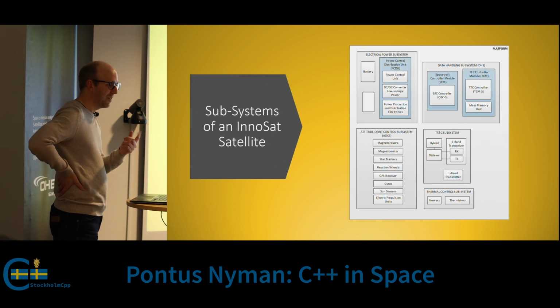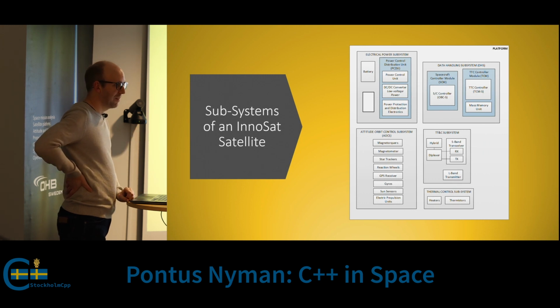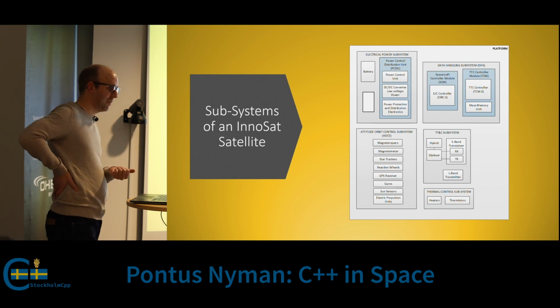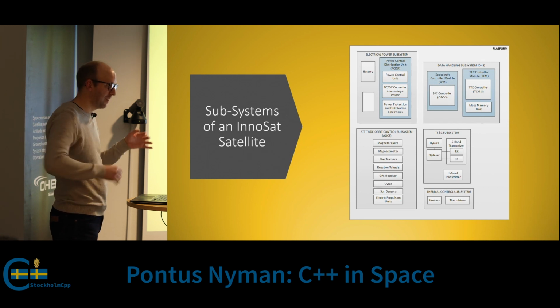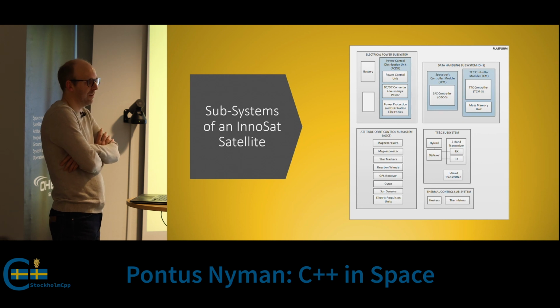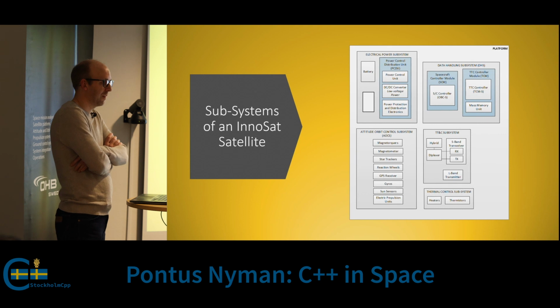A question? Yes. Why do you need to know where the sun is? Can't you just calculate that from some calendar and the orientation? Yeah, we can, but that's more complicated. The sun sensors are really simple. You just get intensity, you have them on each side, and then it's easy to calculate where the sun is. Then you don't need to do some calendar lookup or anything.